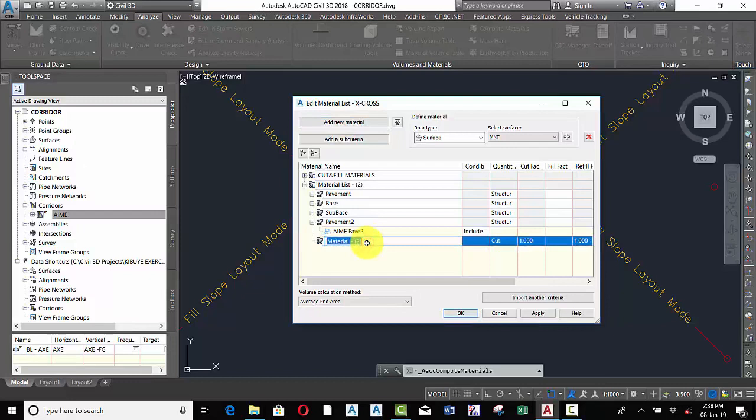And then here I'm calling the sidewalks. As usual, the corridor shape, and then sidewalk structure, add. That's all. It creates a sidewalk.